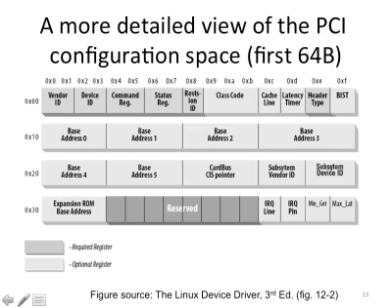The purpose of these addresses is to store the starting address of the components or resources of this PCI device. Because for a PCI device, for example an Ethernet controller, the way it works is it receives packets from the wire. If it's a wired interface card, it'll put them into a small buffer within that controller, within that card. Once the buffer is full, it will push the received packets over the PCI bus to the host memory.